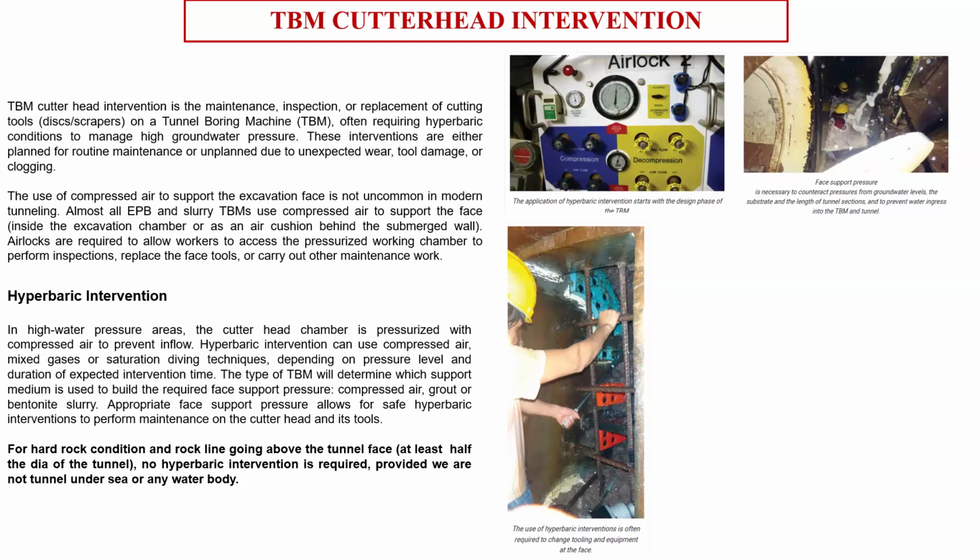So if it is a very tight curve, in one of the projects we got a curve of 250 meter radius. It was around 2018, seven or eight years ago, and the TBM was not so advanced that the tail shield got stuck. When we tried to retrieve the tail shield, even with the articulation system, we were not able to retrieve it.